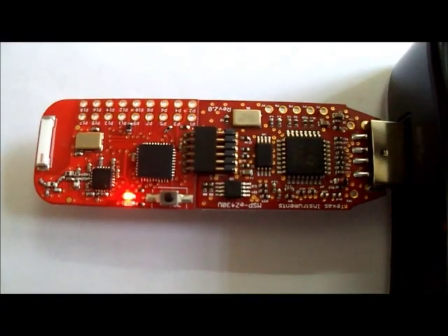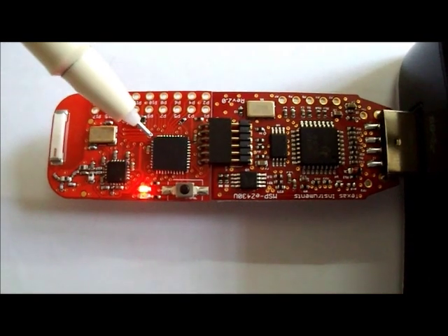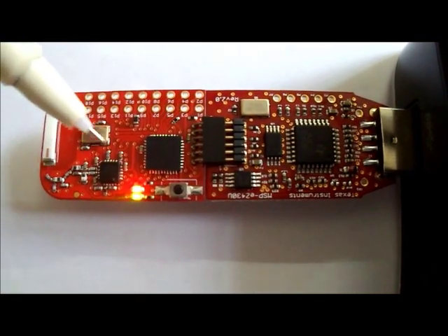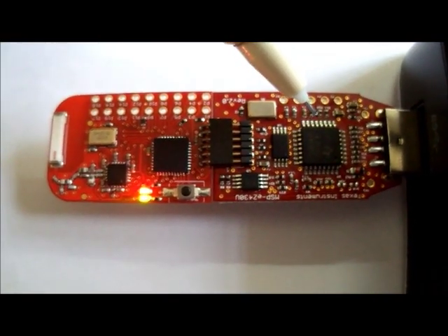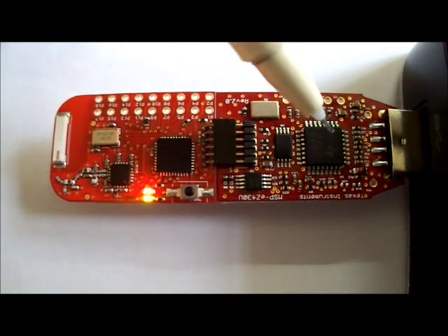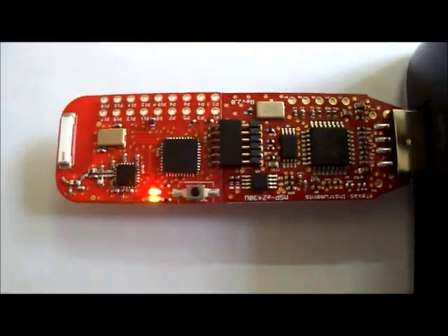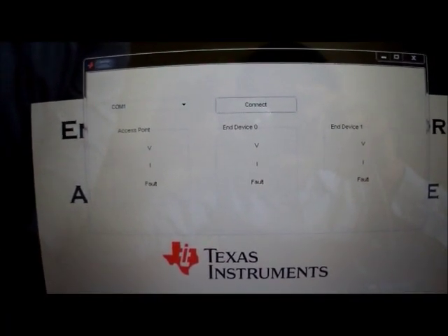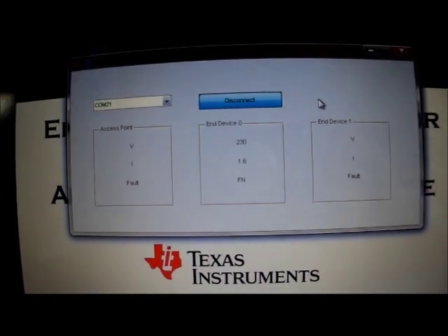Let's see the software part and the microcontroller part. This kit has the MSP430F2274 microcontroller and CC2500 wireless kit. This is the MSP430F16x microcontroller and these are the SPI-Bi-Wire connections with application UART. This is the graphical user interface and it is developed by MATLAB software.